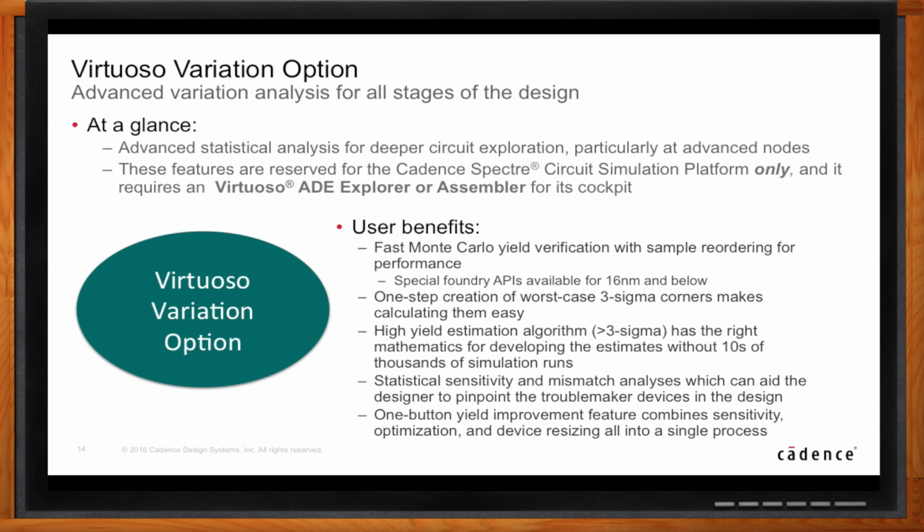The reason why your guys are going to like this, I think, is because rather than having to wait and run long simulations on Monte Carlo, they can go ahead and get these corner files, test these against their design, and see, hey, are we in spec? Are we close to spec? Are we out of spec? Because you know at least these corners are going to represent your worst case world. If you can design within the spec limits, then you know that probably your design is going to be okay. You may still need to run a full Monte Carlo regression at the end. But at least this gives your folks a lot more ease in terms of the design of everyday circuits.